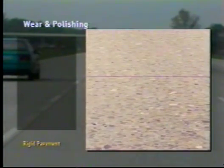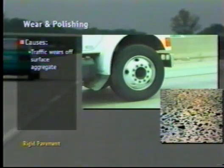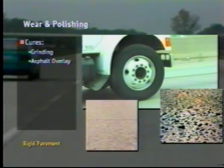Wear and polishing results in a polished surface that can become very slippery in rain. This condition can be quite dangerous. Basically, the traffic wears off the surface aggregates, so a slippery, smooth surface is exposed. To recondition this pavement, either grinding or an asphalt overlay is recommended.